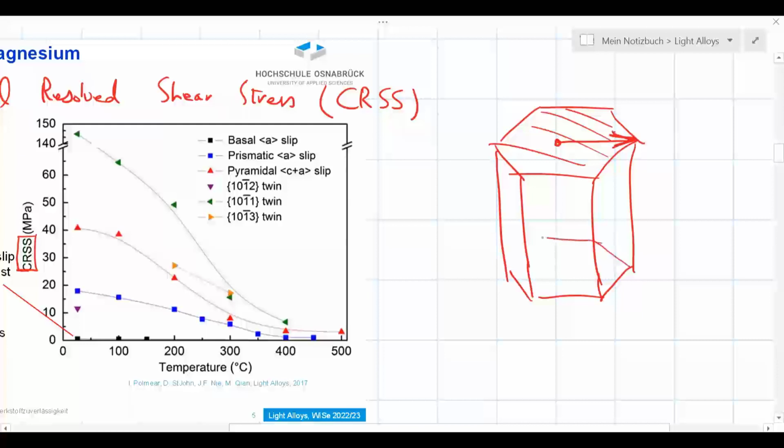All these sorts of planes, and these planes have Miller indices 0001 or 0002. Right? These are basal planes, and they are all parallel to one another. So it is hard to get good plasticity because we are always sliding our material on parallel planes. And this is not a favorable situation in terms of formability.